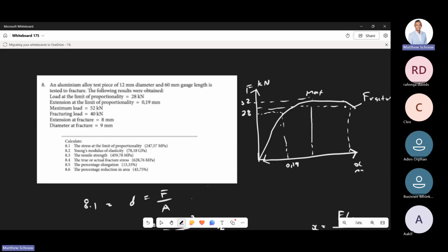So it's more about you must know at which point of the graph you're working with to use specific values. I don't know if I'm clear. Yes. So this over here, they should have called the ultimate tensile strength, and this is typically the max. Then we're talking about fracture, where the specimen breaks. You see what I'm saying to you? So it's at different points of the graph. It's not two conflicting values, it's two different values.